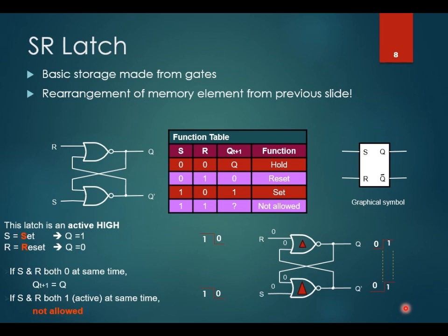The accumulated delay will make the difference bigger, and at one point the pair of NOR gates here will eventually see different values, which is 0 in this case and 1 for the second NOR gate, and it will eventually settle the latch into the stable 1, 0.